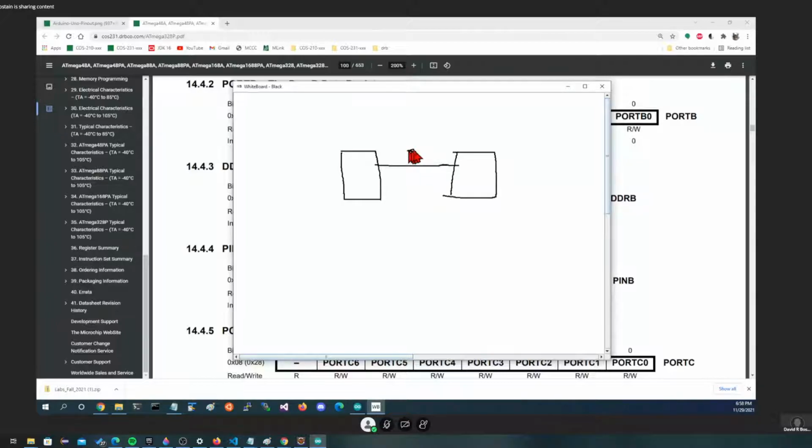So we attach an external pull-up resistor to perhaps 5 volts. Then when neither one of these guys are driving it to ground, anybody else looking at the bus, so he's reading the bus, will see 0 or 5 volts. If they're driving it, they see a 0. If not, they always see a 5 volts. On the ATmega chip, we could still do this, but for our purposes, we solve a different problem.